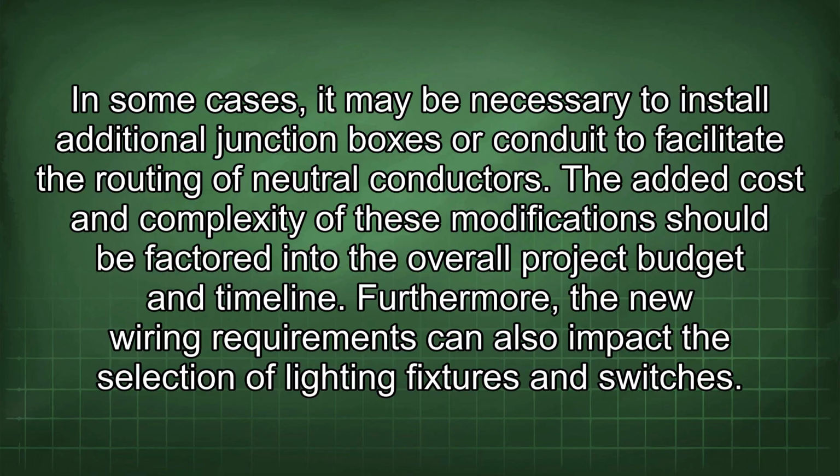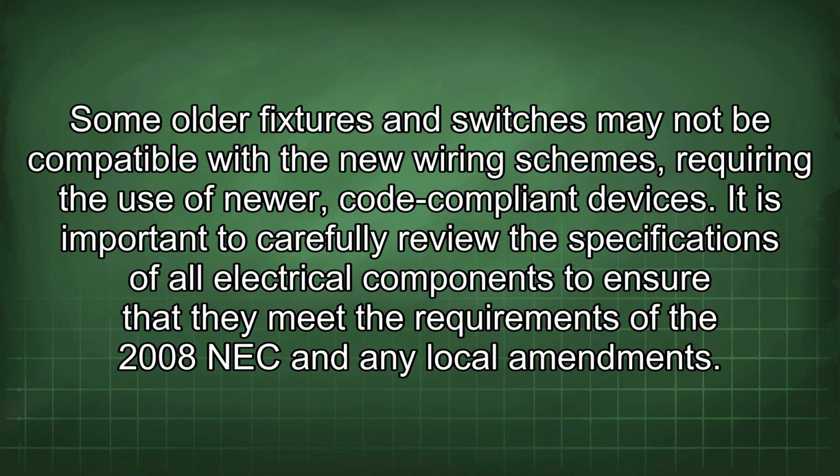Furthermore, the new wiring requirements can also impact the selection of lighting fixtures and switches. Some older fixtures and switches may not be compatible with the new wiring schemes, requiring the use of newer, code-compliant devices. It is important to carefully review the specifications of all electrical components to ensure that they meet the requirements of the 2008 NEC and any local amendments.